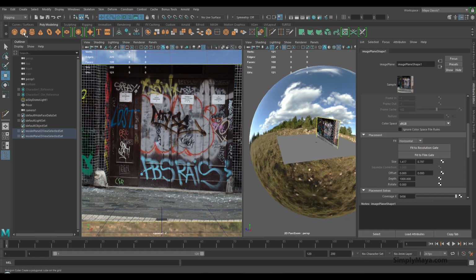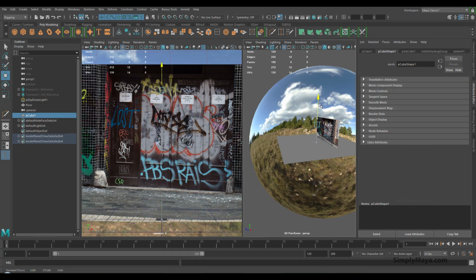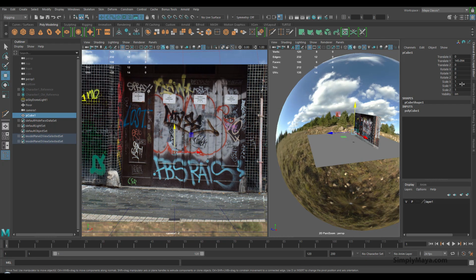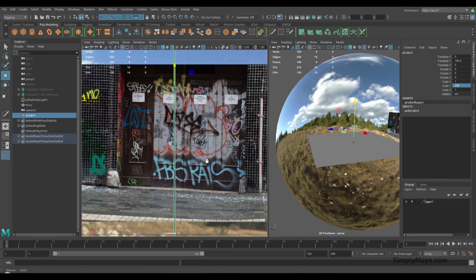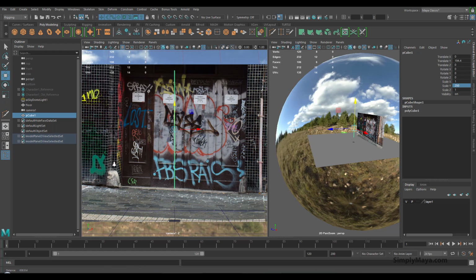So let's put in a very simple box to start the matching process. I'm going to put this somewhere in the middle, tiny box there, and we'll go to its layers and make its height about 2 meters 50. And then we'll move this up here. And yeah, if we were to say this doorway was approximately 2 meters 50, if I actually move the camera in and out, you can see that that then goes in and out. So if I wanted a doorway that was about 2 meters 50, then it would be around here.